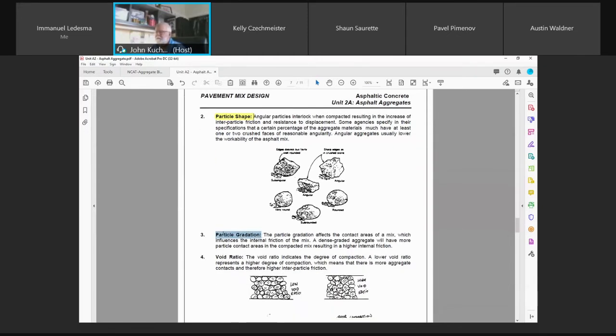Particle shape again. So out of all those, what would be the worst? Would it be the very round or rounded? Round, smooth aggregates would be your worst. Sub-rounded tells you, okay, it was probably angular at one time, but through the environmental forces, it wore down, either by water or whatever. A smooth rounded would be your worst. It's like having a marble. So a sub-rounded would be better than a rounded, obviously, because now sub-rounded means you're getting a little bit of edging, you're getting some edges. But what about the very round and the rounded? Well, the very round, again, would be the garbage.